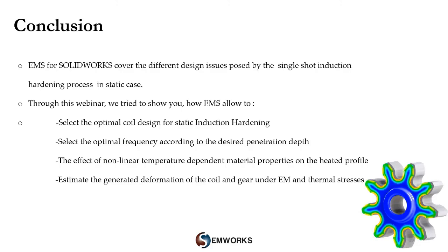Also, the effect of nonlinear temperature-dependent material properties on the heated profile was investigated. And finally, we tried to estimate the generated deformation of the coil and gear under electromagnetic and thermal stresses.